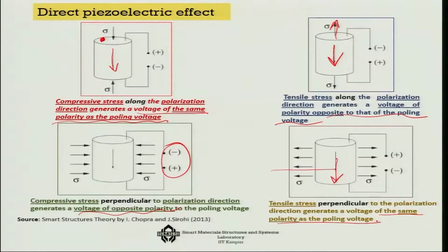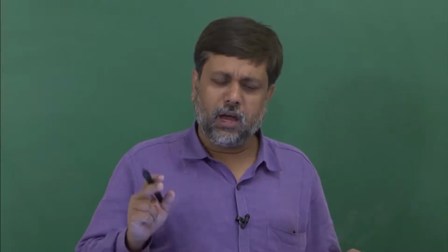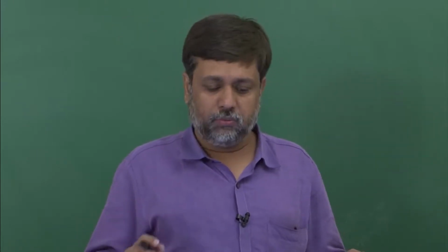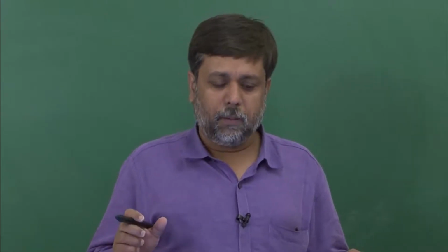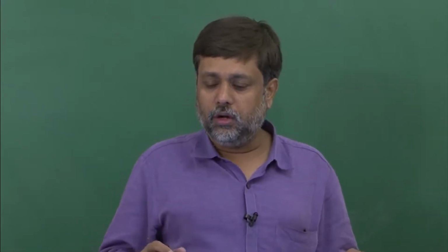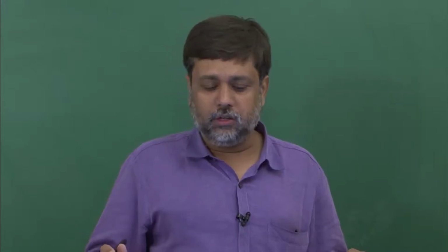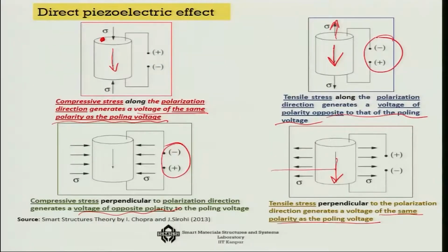If you keep that in mind, direction of compression matched with the direction of polarization is going to give you a positive voltage, and if it is perpendicular, it is going to give you a negative voltage. And in the case of tension, if it is opposite to the direction of polarization, it is going to give you a negative voltage. If it is tensile stress in the perpendicular direction, it is going to give you the same effect as the direction of polarization.